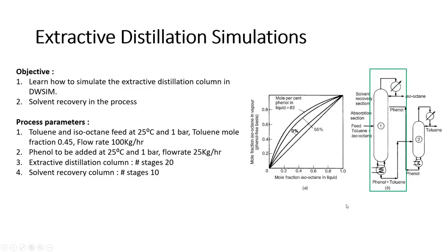So remember, in this flow sheet the phenol is directly recycled back to the column. But what is important is that these two streams should be at the same temperature. Otherwise, depending on the temperature, the other product will be in a vapor phase, and that will affect the equilibrium of the distillation column, and then for the same number of stages and reflux ratio I will not get the same purity of the components and the distillation will be completely different.